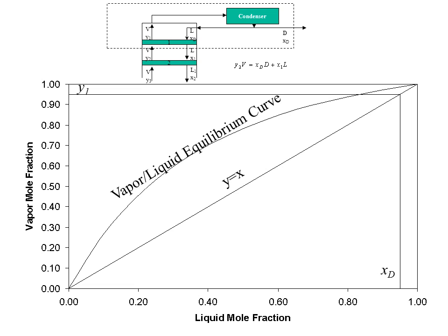Now look at the diagram at the top and you'll see that X1 leaving stage 1 is in equilibrium with Y1 leaving stage 1. And so its composition can be found at the point where Y1 is located on the equilibrium curve. And so X1 can be found, and it's about a value of 0.83 taken from there.